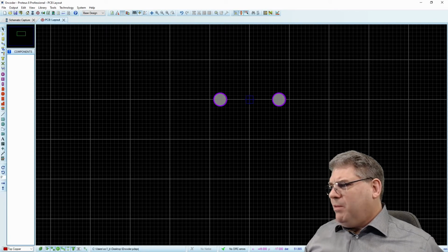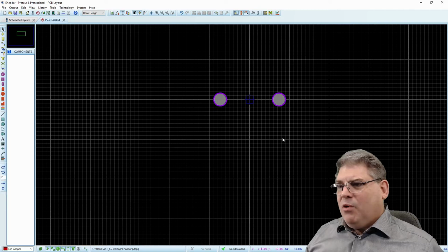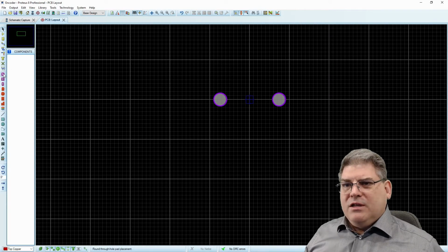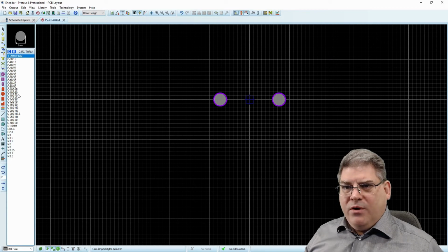So next we want to place the 50 thou by 100 thou pads, and the first location is going to be minus 5 millimeters by minus 10.5 millimeters. So let's pick another pad. We want that was 100 by 50.